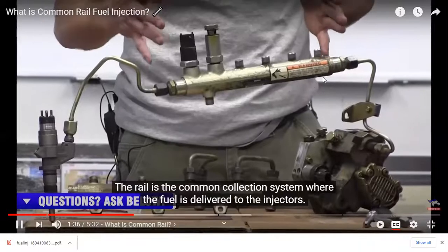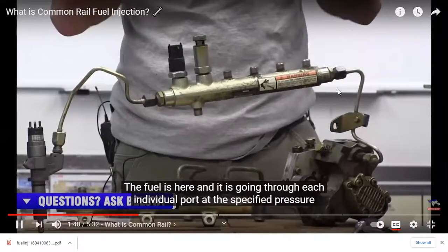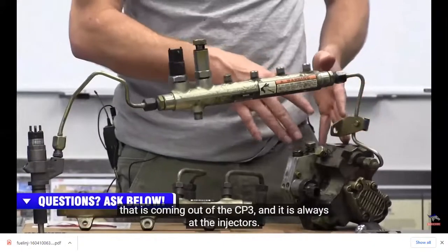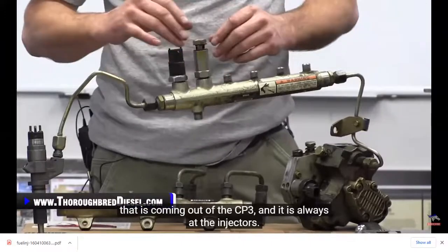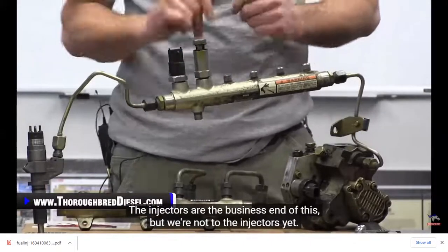This is the common rail. The fuel is here and it is going through each individual port at the specified pressure that is coming out of the CP3, and it is always at the injectors. The injectors are the business end of this, but we're not to the injectors yet.